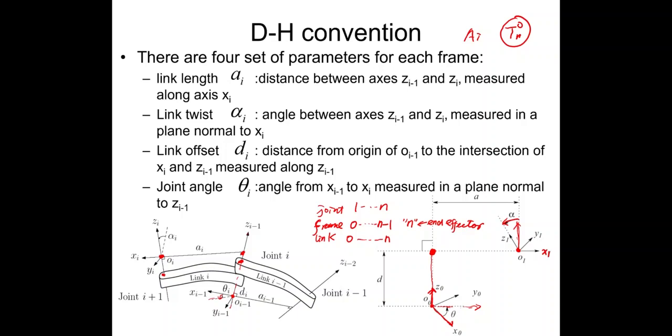So that is the DH convention to define these 4 parameters. The key thing for forward kinematics analysis is to find these 4 parameters. Once we have these 4 parameters, we can quickly calculate the Ai by the given matrix.